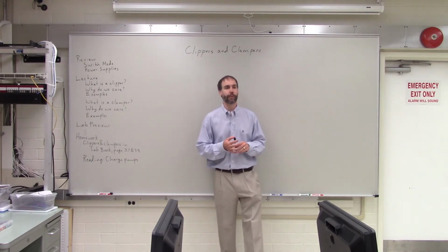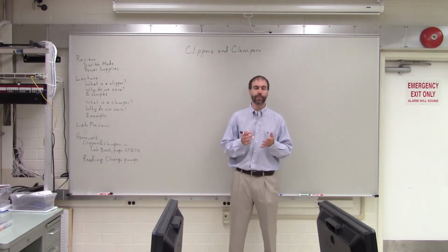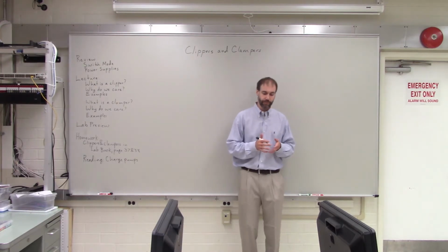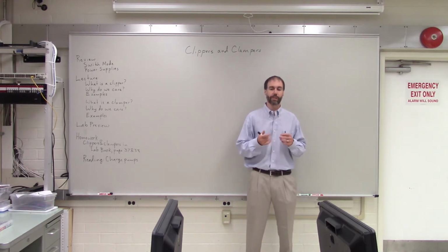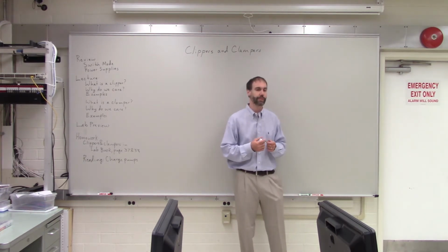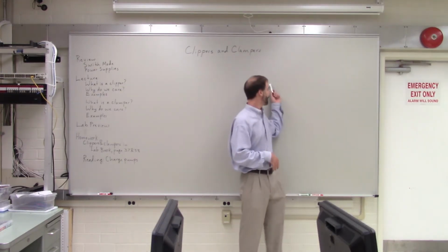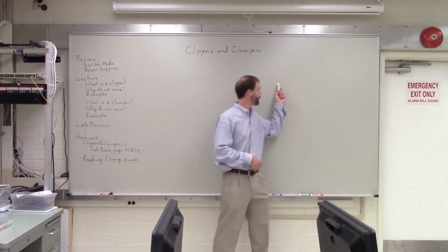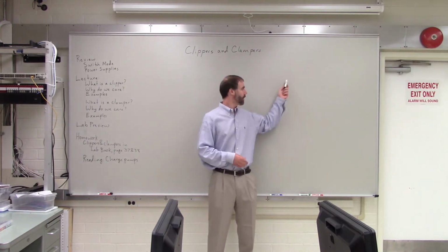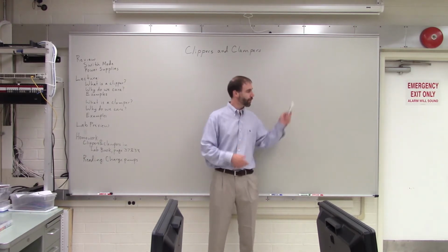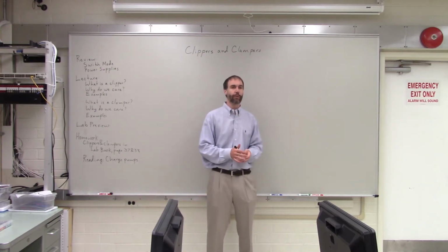Last time we watched a video that told us a little bit about another type of power supply, a switch mode power supply. The basic idea behind switch mode power supplies was that they would take an input that was the filtered AC signal that still had a ripple in it, and then increase that and turn it into several DC output voltages.